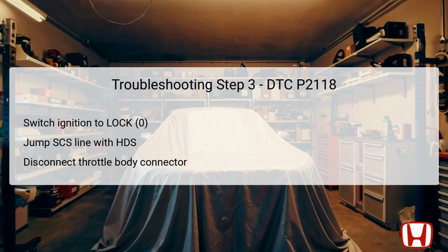Next, the technician should jump the SCS, service check signal, line with the HDS. This process is crucial for enabling the diagnostic tools to read data accurately and conduct further tests effectively.